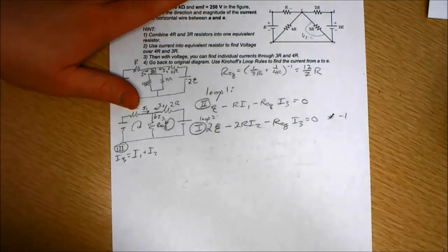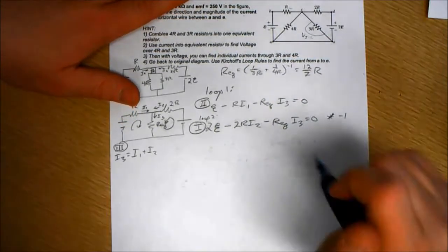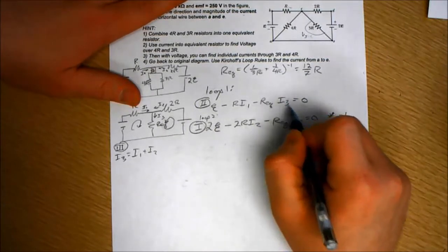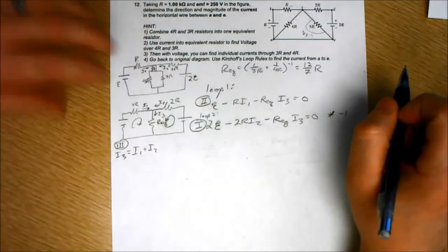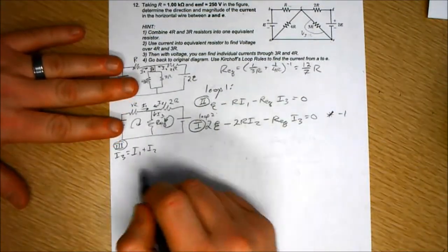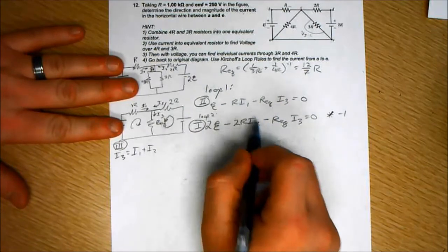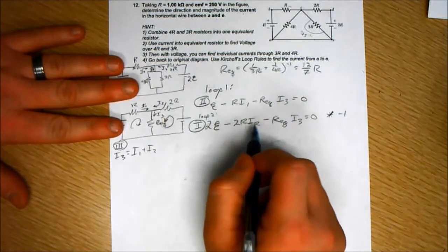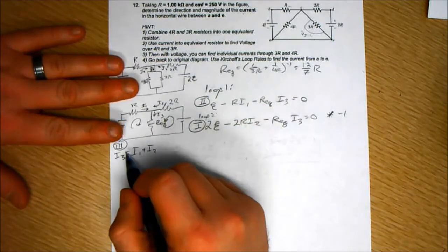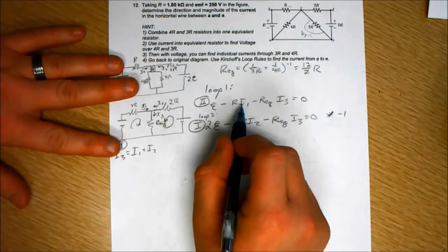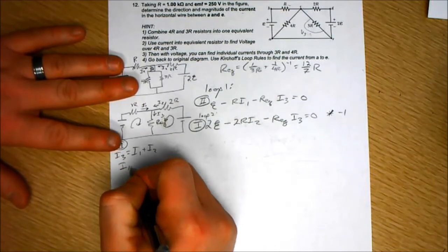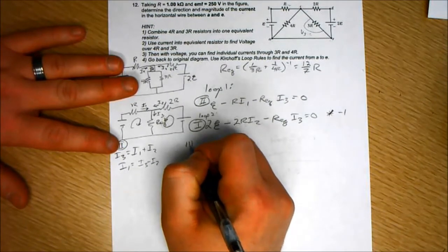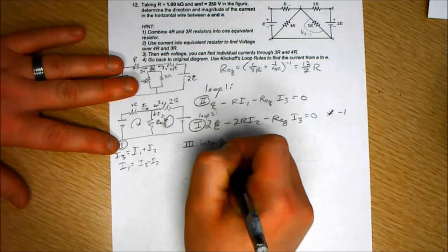So what do we do? Well, if I look at equation 2, we have I1, I2, and I3 in these two equations. Now that I have my three equations defined, I'm going to eliminate one of these variables from these two equations. I have I3 in both, so I can't deal with that, but I have I1 and I2. I can use equation 3 to eliminate one of them. Let's try eliminating I1. So I1 is I3 minus I2, and so I'll take equation 3 into equation 2.